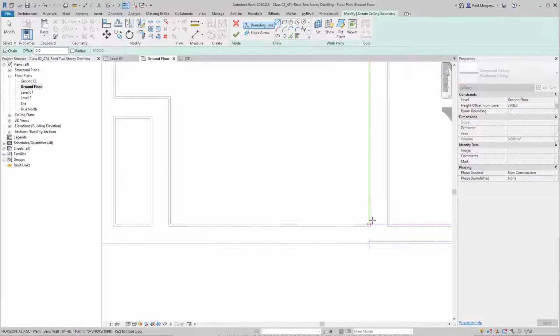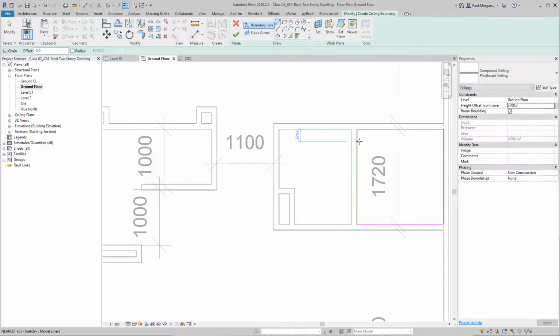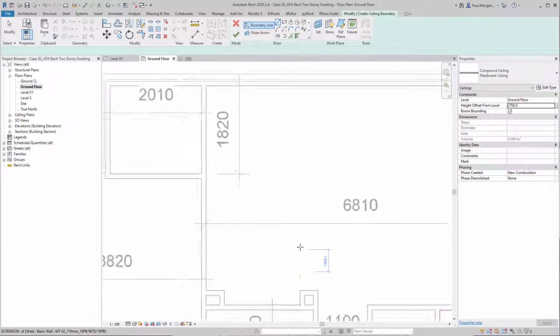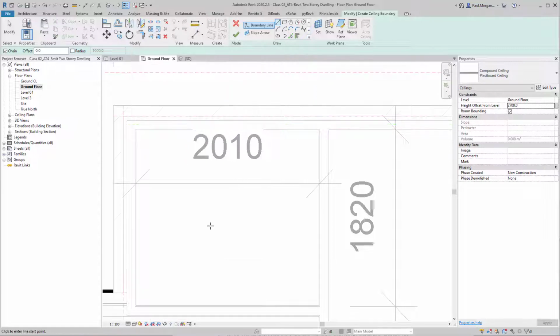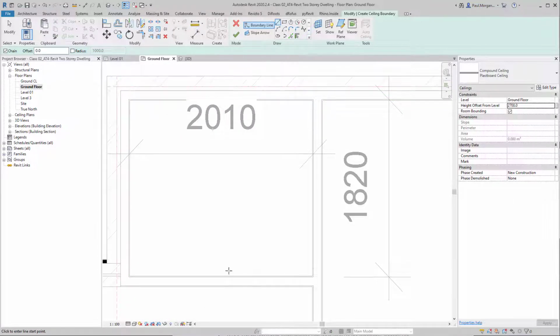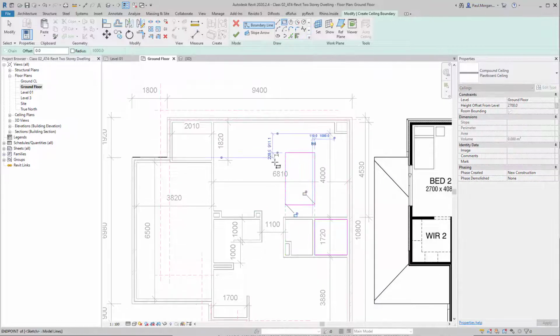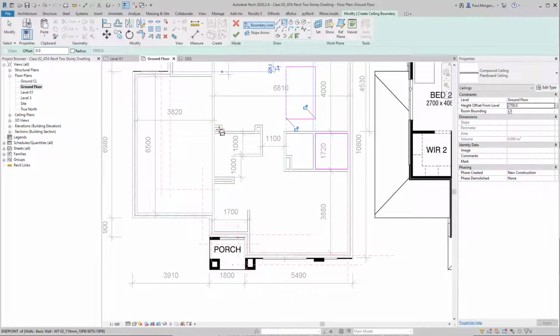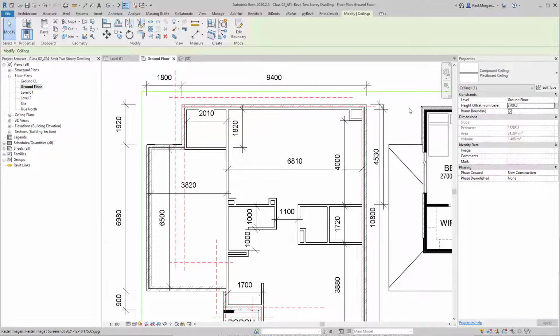You'll notice as well that when I get to the end of a room, that's one completed sketch. We can see that there. I then continue on, and any room with wood doors, we haven't put in doors yet, doesn't really matter, you just keep going over that. But if I was to do two boundaries in the same sketch, so let's say I got this area here, and I'll just roughly do the garage as well. So I got the garage. And then when I'm done with that, I would then click OK, and those ceilings are created.